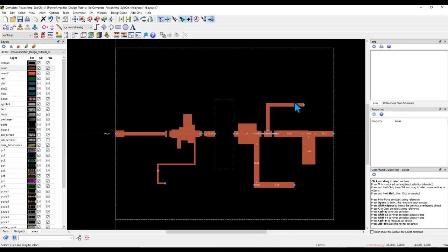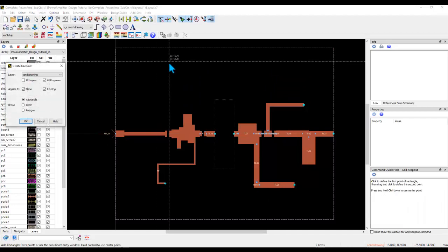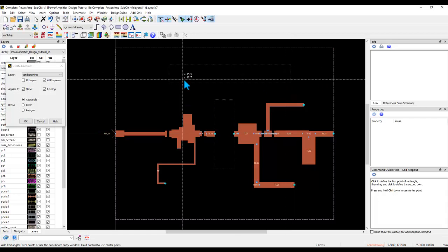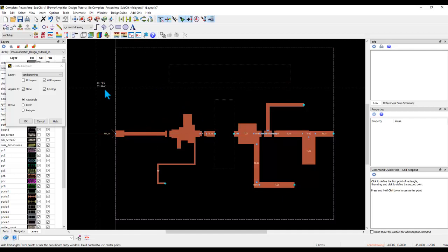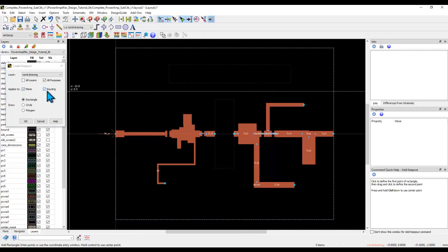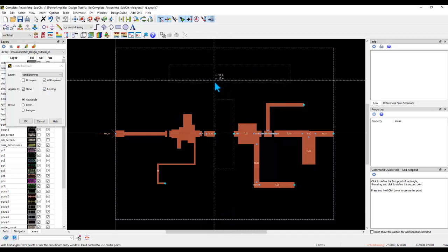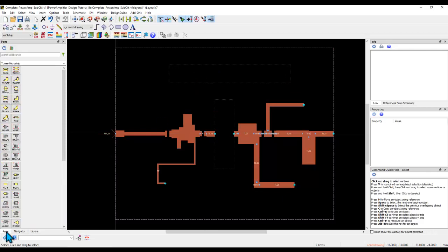So now we have our short circuit stub, we have our line bends. You can see everything is nicely filled up. I will add one more keep out, somewhere here, and that is the region I would like to put my text. All right, and again, I have barred any plane interfering into my keep out or any kind of routing in case you're doing any additional routing on the board. So nothing will go inside this keep out.